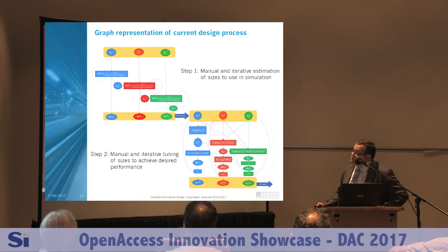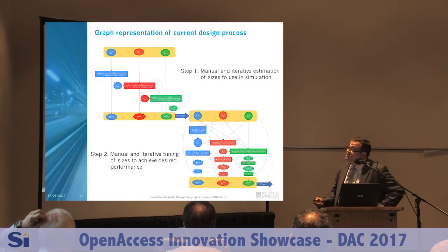computational effort. But the designer, in order to use the simulator, first tries to get an initial guess for widths and lengths. So he does something much simpler. He takes the first order model of the transistor, he computes a width, and then a polarization, and he moves to the second transistor and so on. So we thought about developing a methodology that is based on this approach, which has a low computational effort, but can benefit from the accuracy of the simulator approach. So we have a fast approach with the accuracy of the other approach.